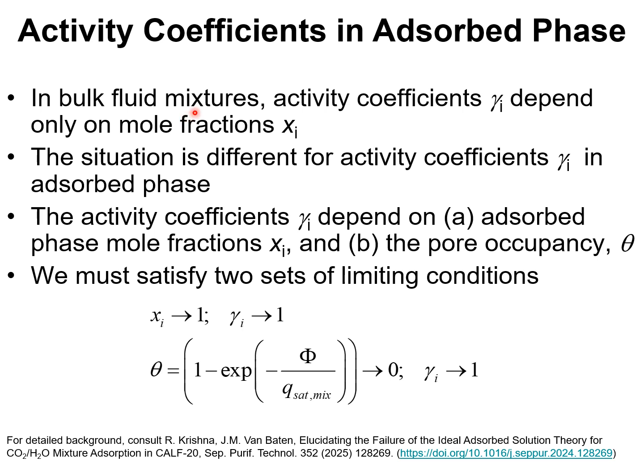In bulk fluid mixtures, the activity coefficients depend on the mixture compositions, say mole fractions xi. The situation is different for activity coefficients in the adsorbed phase within microporous materials. In this case, the activity coefficients of any component i depend not only on the adsorbed phase mole fraction xi, but also on the pore occupancy. We must satisfy two sets of limiting conditions.